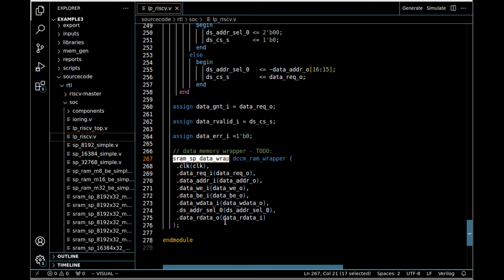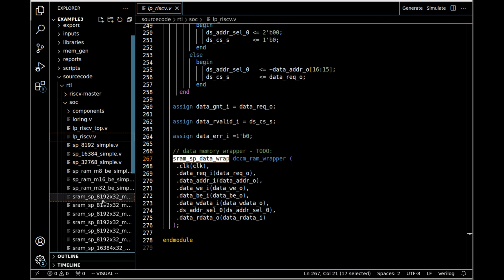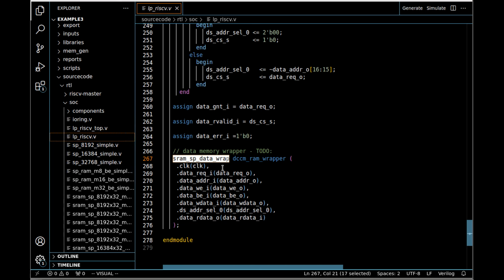These both just have two other layers of abstraction of wrappers, so I don't have to discuss exactly what the ports are and what the size of the SRAM is. I can use kind of generic signals, and depending on how much memory I want to put in and who the provider is of the actual block of memory, I put those inside these different wrapper levels to abstract it away and make changing these things a bit easier. Okay, so that is all I have in my SoC.